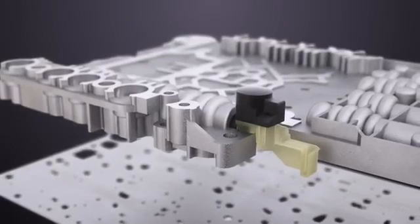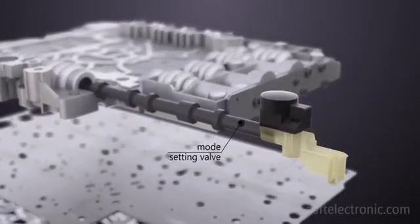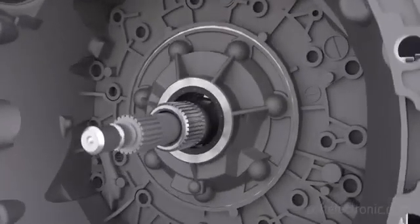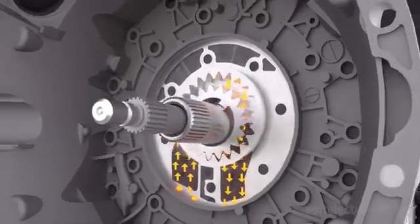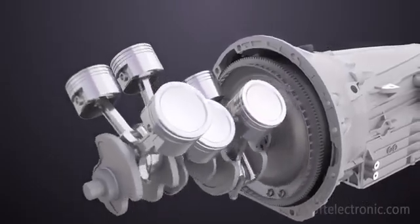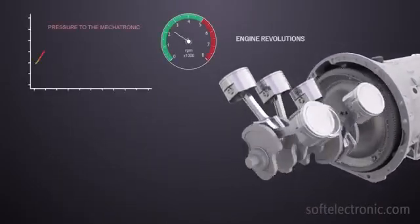In the upper plate is the manual valve, which determines whether the car is in parking, drive, neutral, or reverse position. The fluid pump is firmly attached to the crankshaft of the engine via the torque converter housing. Because of this, the fluid which is fed from the pump to the mechatronic has variable pressure depending on the revolutions of the engine.